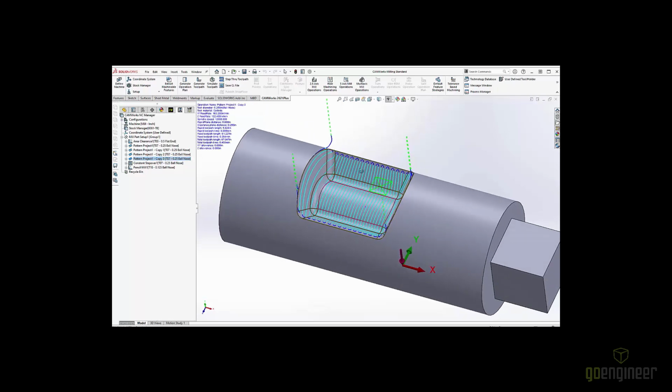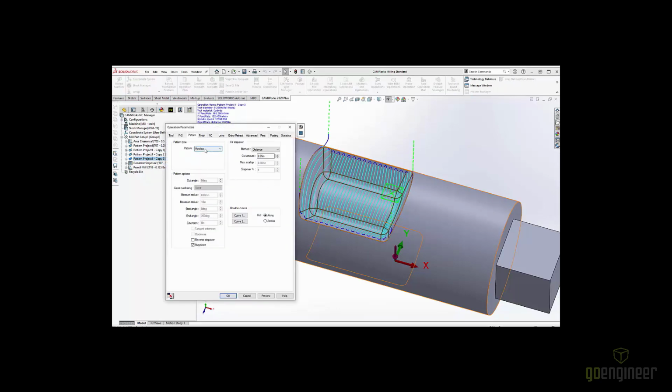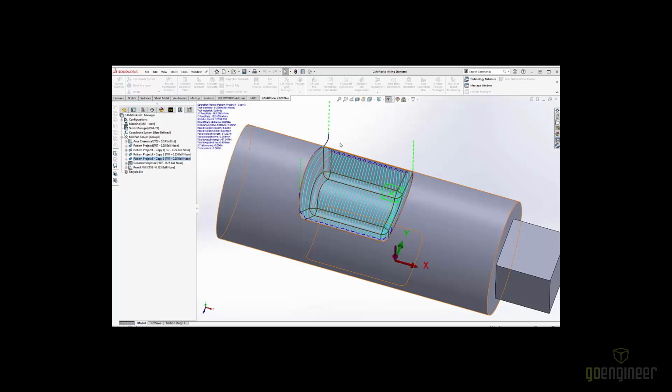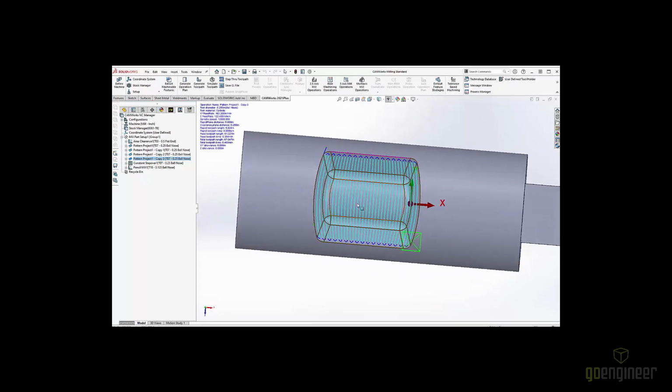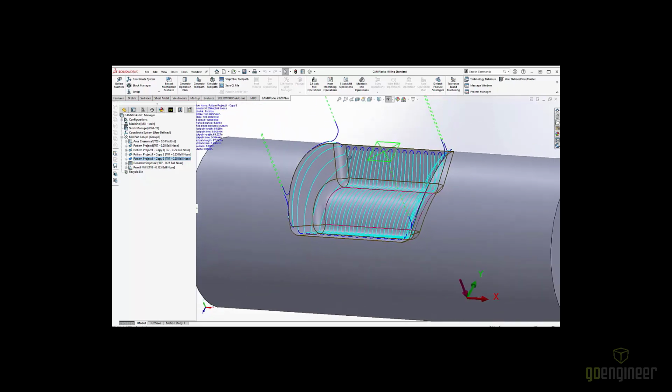And then we lastly have what we call, it's my favorite, using the curves of the part, using the geometry of the part through what they call flow line. I can actually determine curves to follow along. In this case, I chose the two left and right ends. You can see how the curve kind of matches those left and right edges, and they slowly morph between one another as they travel from left to right.